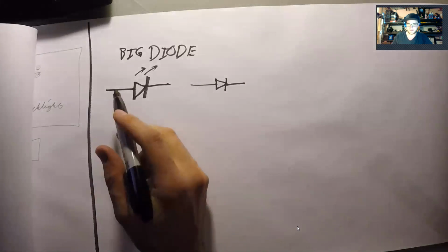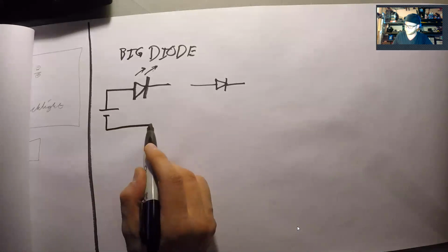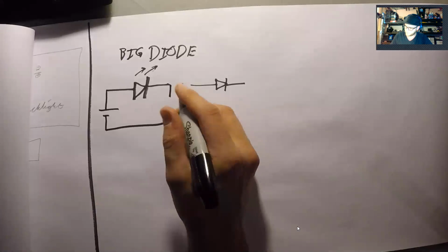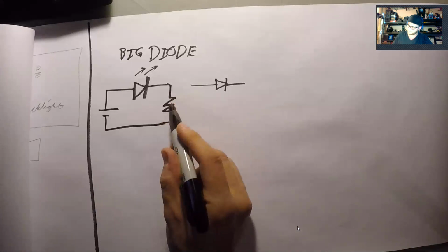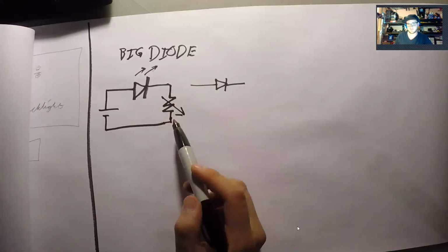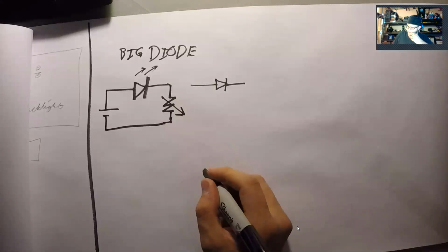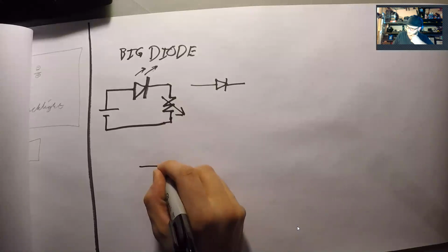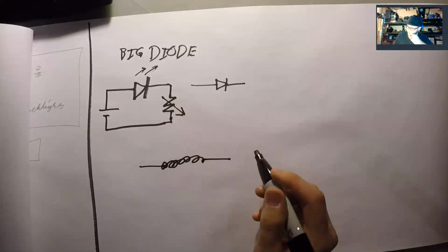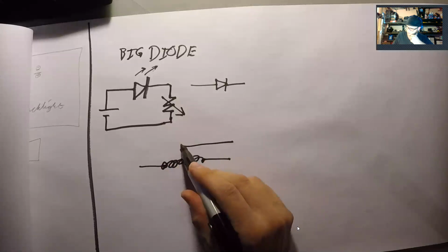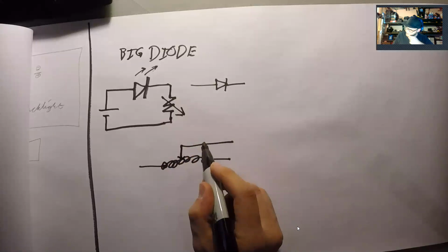So if you have your circuit, and you have a resistor in there, a rheostat, the symbol is like this. So it's just a resistor with an arrow through it. And so what this is, it's a physical wire winding. And then it has what's called a wiper in line. And this is on a movable armature.